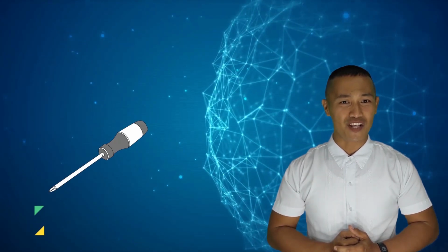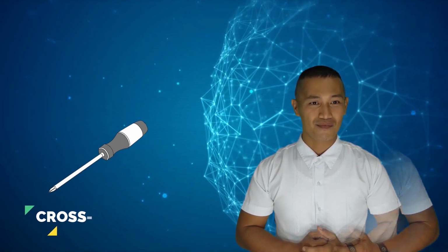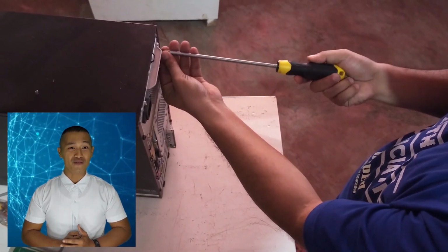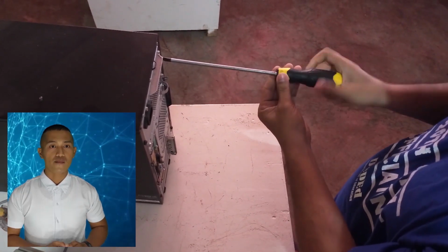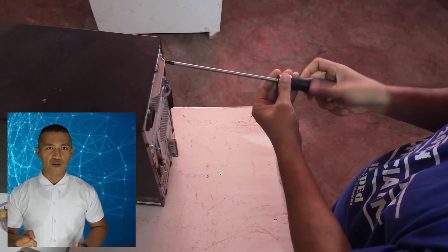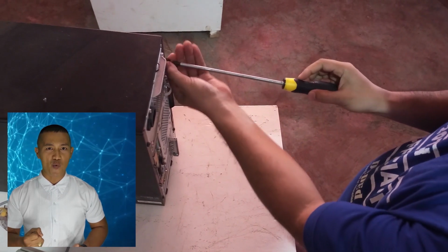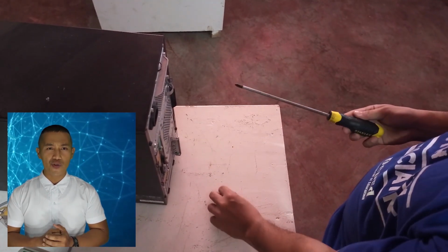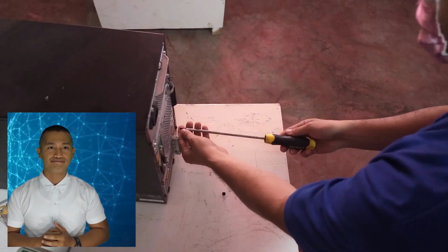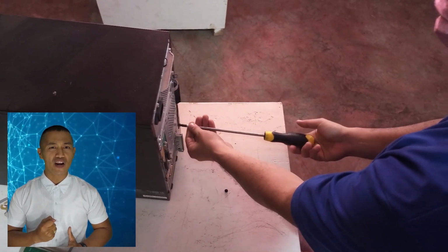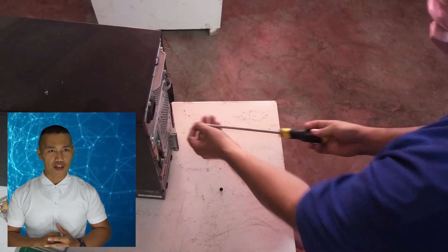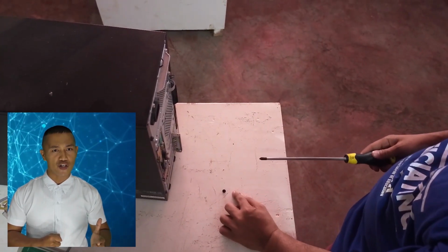Cross screwdriver is used to loosen or tighten cross head screws. Hold the tip of the screwdriver with one hand as you turn its handle with the other. Grasp the handle with your dominant hand and the tip with your other hand as close to the head of the screw as you can. Apply enough force to turn the screwdriver clockwise to tighten the screw and the opposite direction to loosen it.